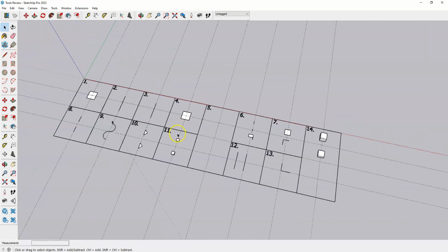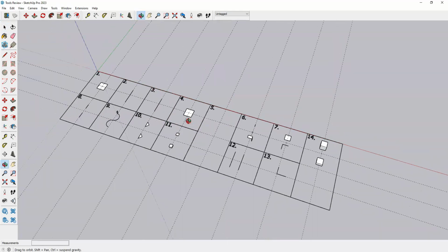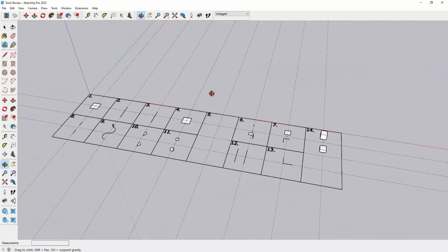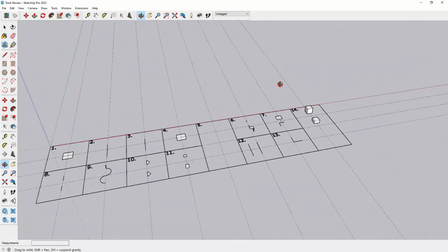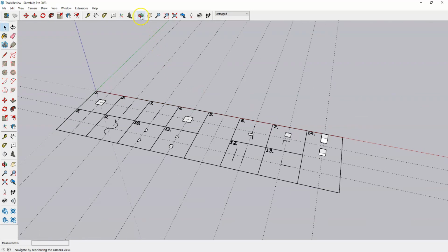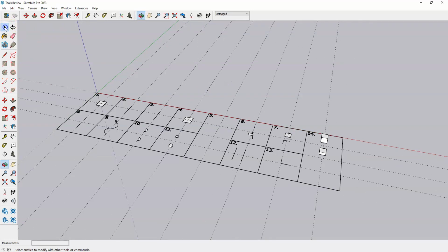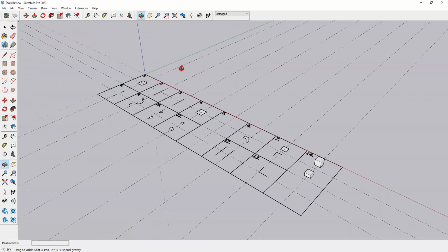I think I also have written in there that you can push and hold your scroll tool, and the orbit tool automatically will be activated, so then you can orbit around that way. Of course, you can also come up to your toolbar and click the orbit tool, but sometimes it's a little bit quicker to just press and hold that scroll wheel.